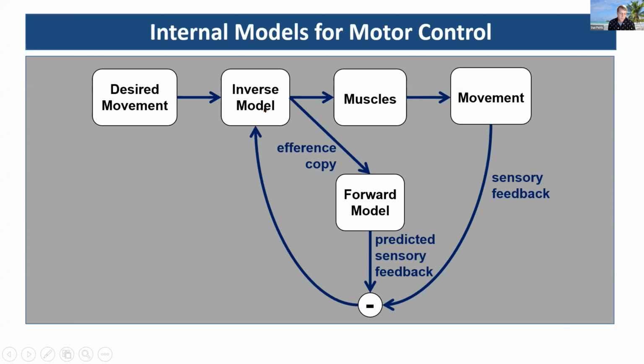There are some really nice experiments by Daniel Wolpert, who has looked at what happens if you play around with human-machine interactions by delaying the robot assistance to you. What he found is, if you get even as little as 100 milliseconds, you start getting a change in how your brain is perceiving that assistance. And when you get up to 200 or 250 milliseconds, you no longer perceive it as part of your motion, and it's some external agent that's doing it to you. So reducing this lag time in the control is super important for future devices.